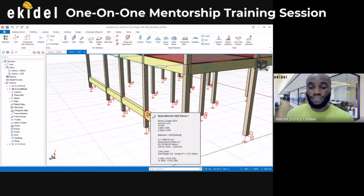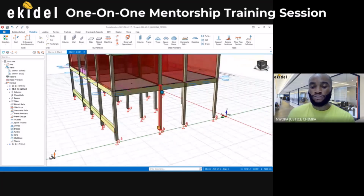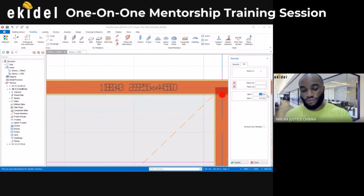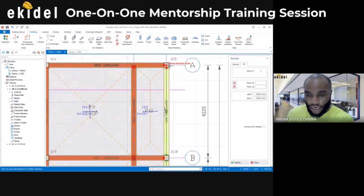So I'll use the same way to insert all other beams where I want to connect or have a plinth beam. I'll come again, same thing, click on this beam, normal beam. Again, come here, set it minus 3300 going down. Okay, that's fine. So I'll do the same thing from here all the way down.